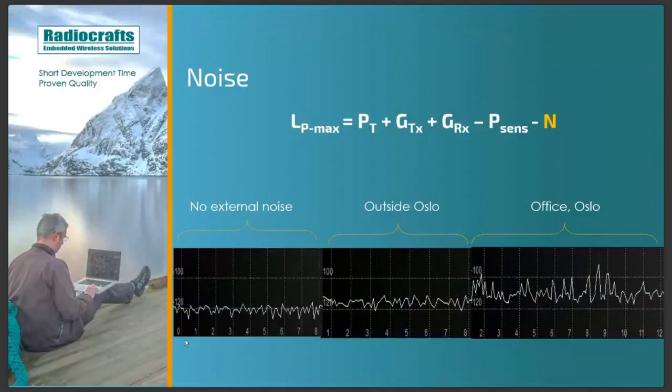The reason we still received them, with zero packet loss at that position, is the acknowledgement and retransmission in the protocol, which ensures that even though we lose one packet, we retransmit and get the next one through. With this noise pattern in the real world, that feature is very important. Other radio technologies, typically Sigfox and LoRa, are basically shoot and forget, where you don't confirm that the packet gets through, so you are more dependent on being lucky, I guess.